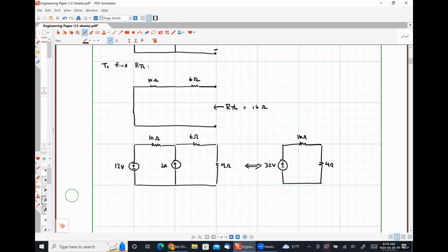It effectively does the exact same role as what we were doing with source combinations on Monday's class meeting, except that we can use it when we can't actually use a source combination, right? So when we were doing our maximum power transfer theorem stuff there at the end, we were using multiple source transformations to get our circuit down into a state like this where we had a practical voltage source or a practical current source connected to our load resistor.